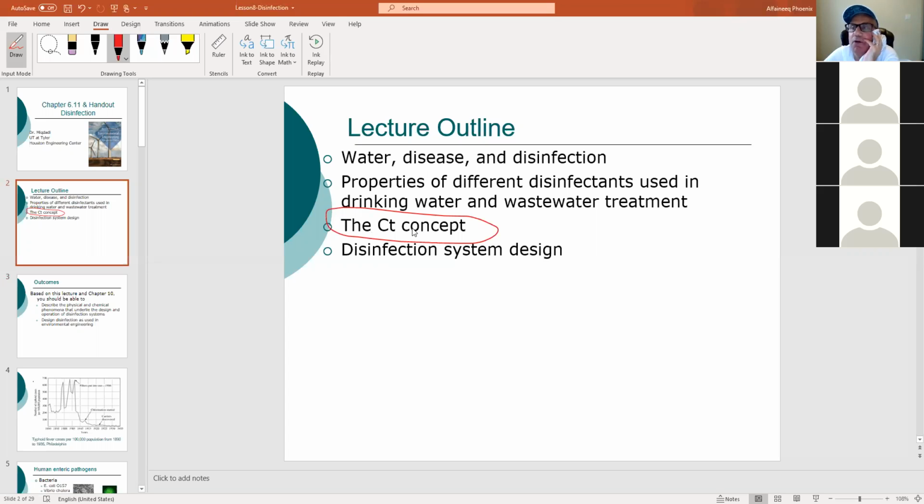You calculate the log inactivation. I give you the concentration. This is the concentration of the disinfectant, okay? Let's say that's chlorine. Disinfectant alone with its concentration is not enough to inactivate pathogens, microorganisms. You need a time of contact. You need to leave it there for a given period of time so it's going to work. Otherwise, it will not.